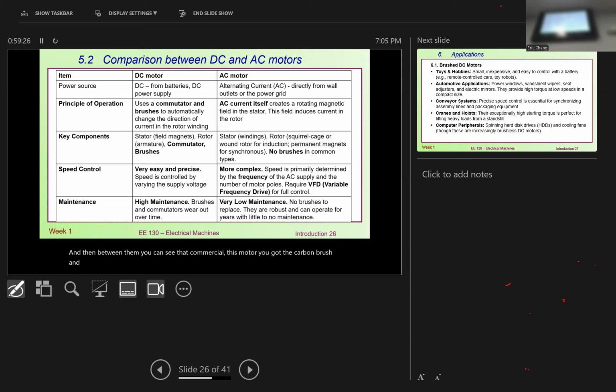This connects the electrical power to the winding. Because when the motor rotates, we need to continuously supply the winding. We need to switch the winding at a 180-degree phase angle. So that's why we do need a commutator. The conventional DC motor needs to use a commutator, and that's one of the disadvantages of this motor.